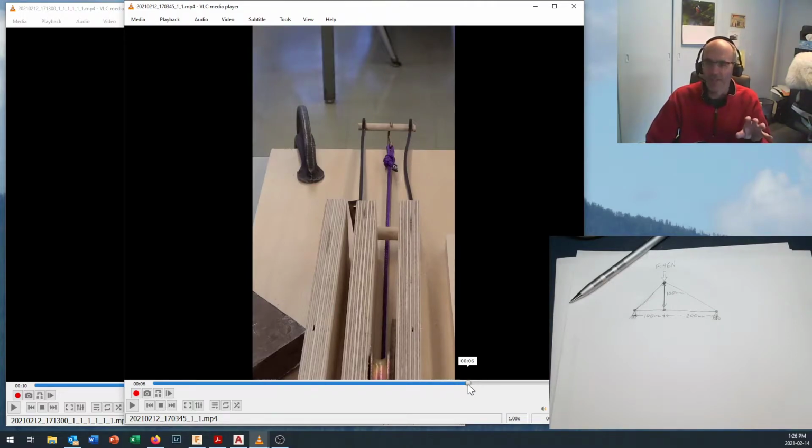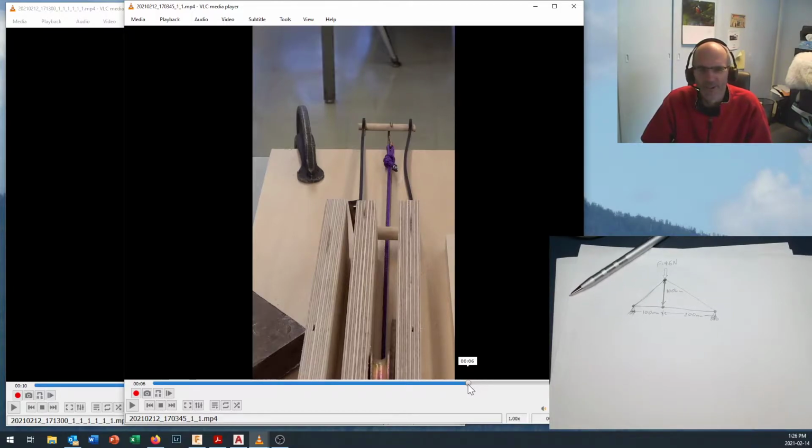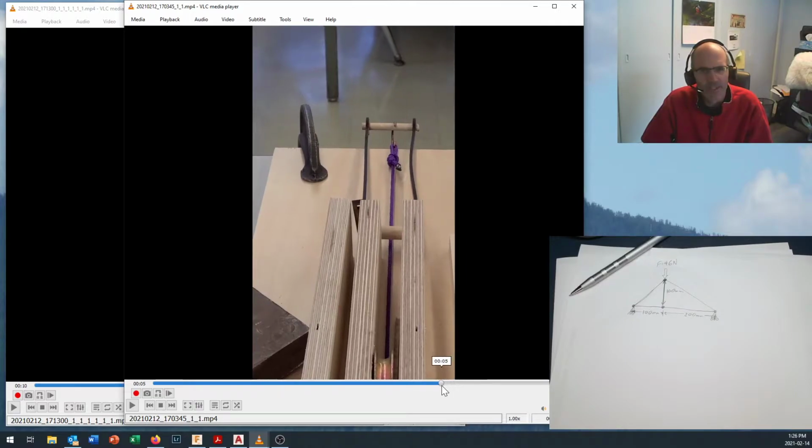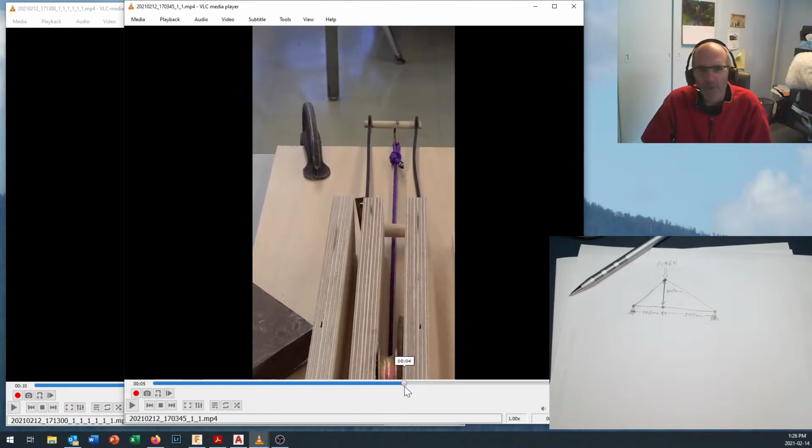But actually, it held just about the same amount. I think we were at like 9.7, 9.8 because I was doing the test all by myself and just sort of jury rigging it. I didn't have the fish scale in the frame while I was doing this, so I don't have a perfect test on here. But you can see that one again, we've got a straight bit, and then we've got a C coming together in there. So two interesting different failure modes, both at very close to the same amount of load,